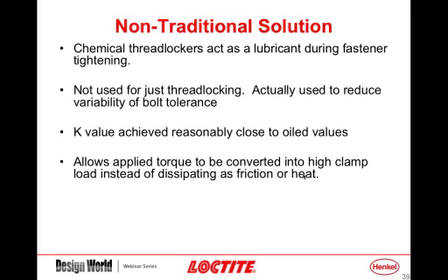So again, those two studies that we did were showing that only about 10 to 15% of the torque value is going to generate your clamp load. So if you are going to be changing your friction or K factor for the system by the thread locking system that you select, you do need to probably adjust the amount of torque that you're going to put in.